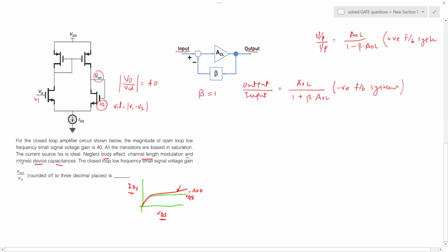So this is generally the system when your amplifier becomes an oscillator, which you don't want. Or you purposely design an oscillator, so your closed loop transfer function should take this form. In the present case, your closed loop transfer function should take this form, which is the case here. So plus sign for the negative feedback and the minus sign for the positive feedback.